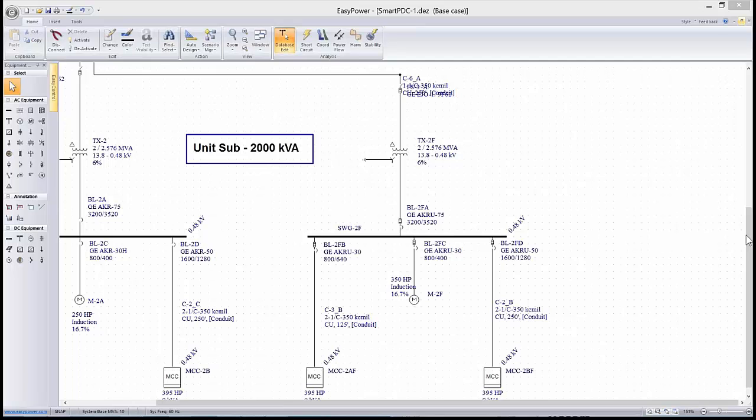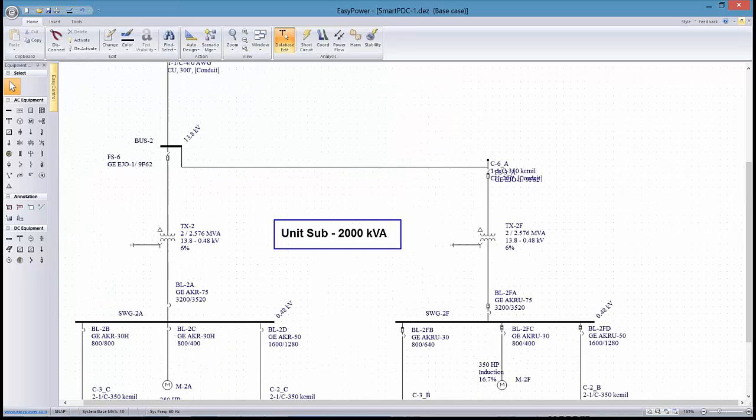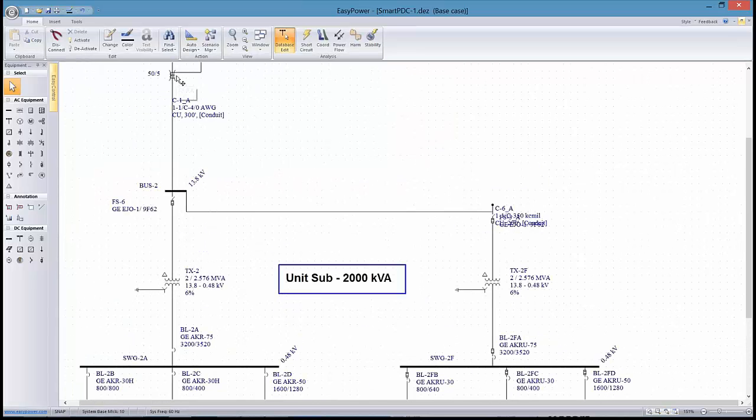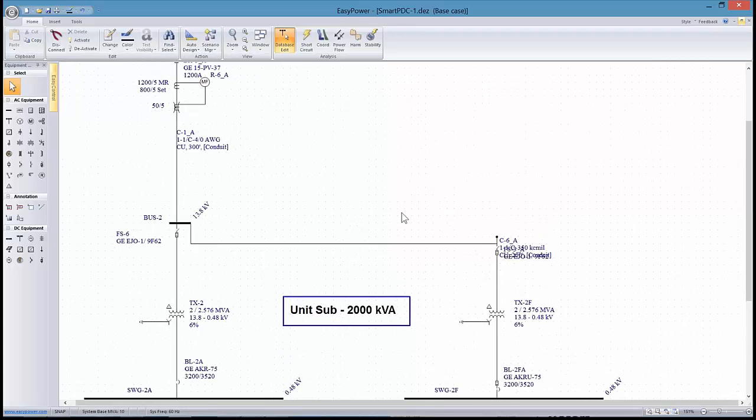The question is, inrush primary current? The answer is yes. And that was probably misleading on my part, because the reason for showing it was actually just the function of the relay that was being used. But the answer is yes. So the protective device will be on the primary side, and that's where we really need to be making adjustments. So I apologize for that faux pas. What I was trying to show is just the function of the relay and how it applies to different points on the TCC curve.